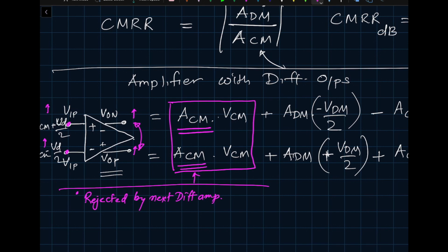And what is this really doing? A small variation because of the input common mode change will only change the bias point at the output. If the bias point changes too much, then it may impact the small signal gain of the next stages.